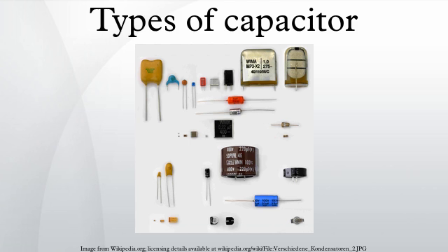For antique radio equipment, preconditioning of older electrolytic capacitors may be recommended. This involves applying the operating voltage for some 10 minutes over a current limiting resistor to the terminals of the capacitor. Applying a voltage through a safety resistor repairs the oxide layers.